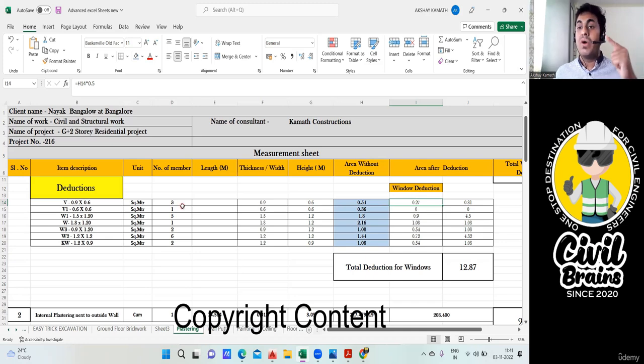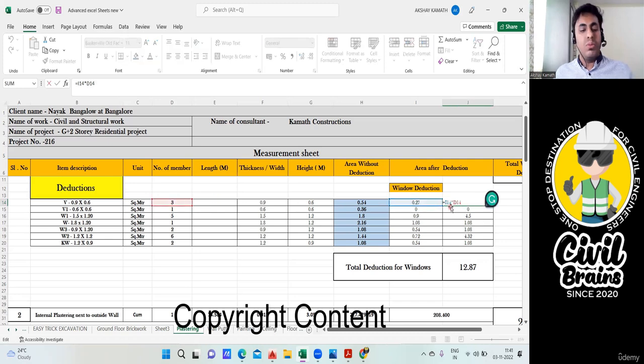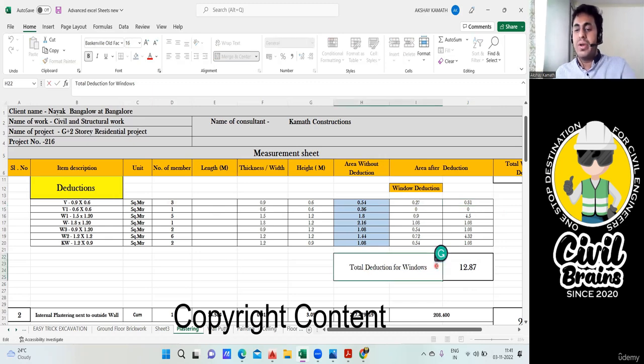Now, if you're doing for one ventilator, for all the three ventilators, 0.27, 0.27, 0.27 will come. So I'm multiplying it by 3 times. 0.27 into 3 will give me 0.81. Got it? So now the total deduction for the windows and ventilator. Okay, this is total deduction I should write, not for windows, because even ventilator is also coming.